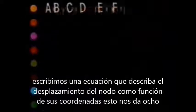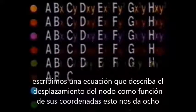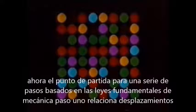In this example, the elements have 8 nodes, and for each of these, we write an equation describing the displacement of the node as a function of its coordinates. This gives us 8 equations for the whole element, which together form a matrix. This matrix is now the starting point for a series of steps based on the fundamental laws of mechanics.